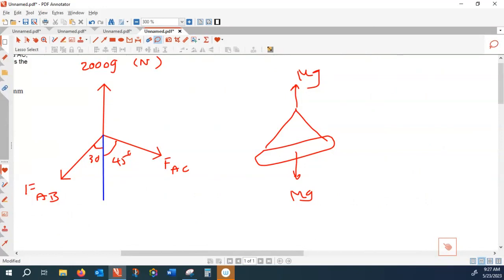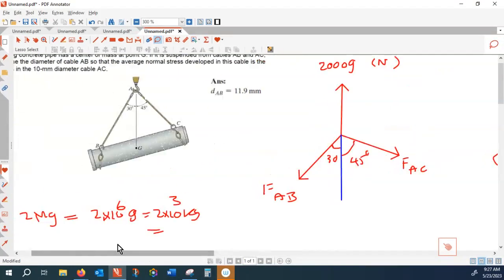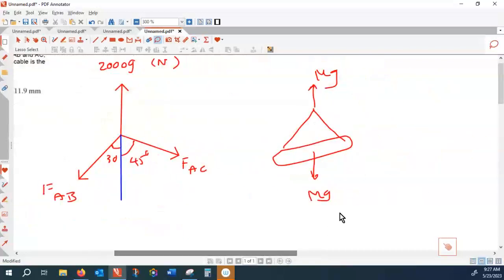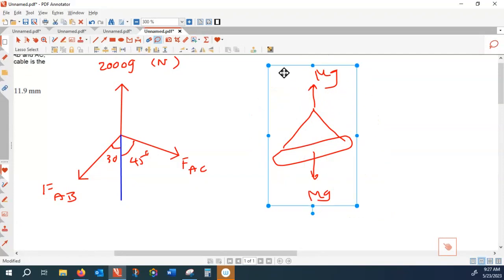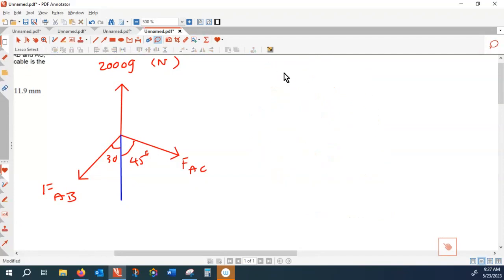And then the second free body diagram is when you are cutting through the cables, so now my envelope is like that. So I'm cutting through the cables. The internal forces are exposed, and also the hook action reaction. Okay, so now the solution is up to you. You either can do it with the Cartesian resolving the forces, solving two equations, two unknowns, or you can construct a triangle and use the sine law. So let's do the sine law again.